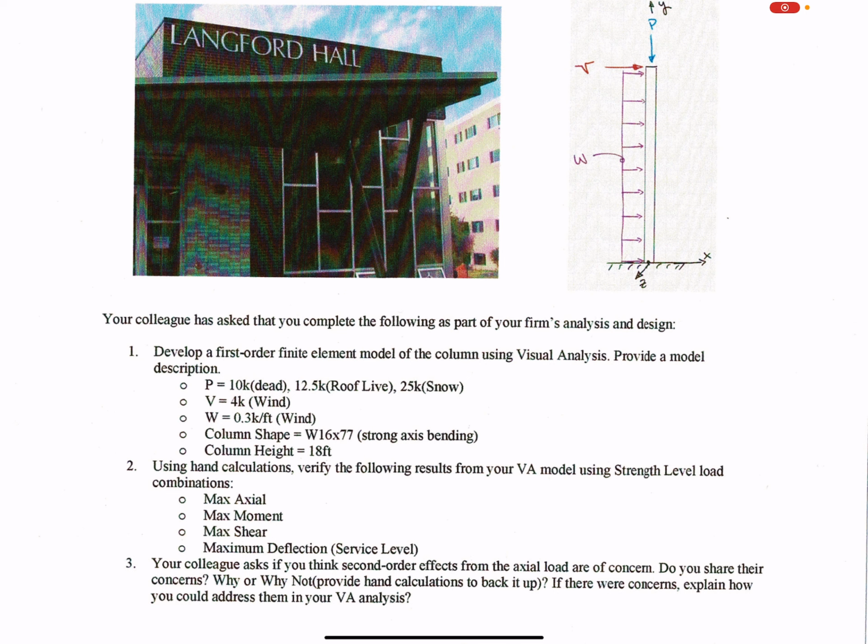Not as efficient or as accurate in some instances as the LRFD method, but it's still commonly practiced in those two materials, masonry and wood. Maybe someday in the NDS... did Damon teach wood? Did he talk about how there's LRFD in wood that you can utilize? Similarly, the steel manual does everything twice. It does ASD and LRFD, because there are a lot of holdouts who just like their ASD. So that was one thing: making sure you use service level demands when you're calculating deflections.